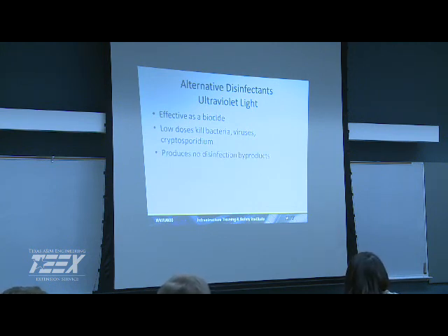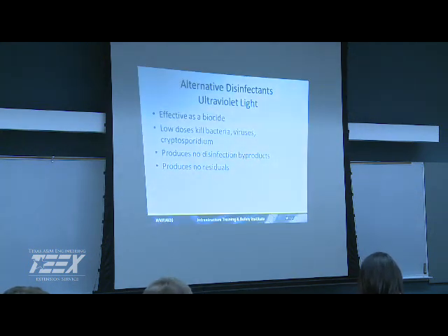You don't get any disinfection byproducts because there's no chemical reaction. It's just like what's happening in your skin. If you're out in the sun too much, you're mutating your DNA, and that's what it's doing to the microorganisms. It doesn't produce a residual, so you can't use it as a final disinfectant in your distribution system. That is disinfection. Questions, comments?